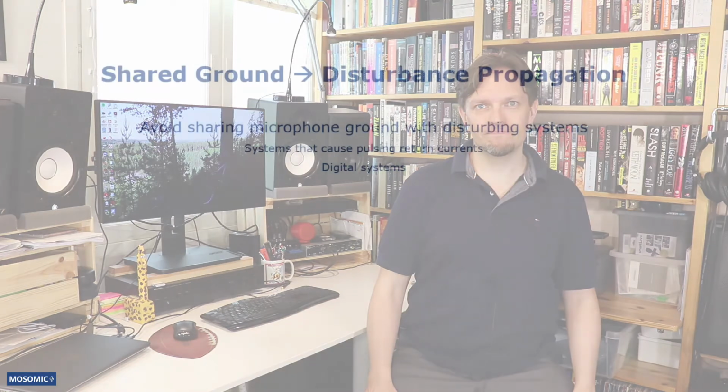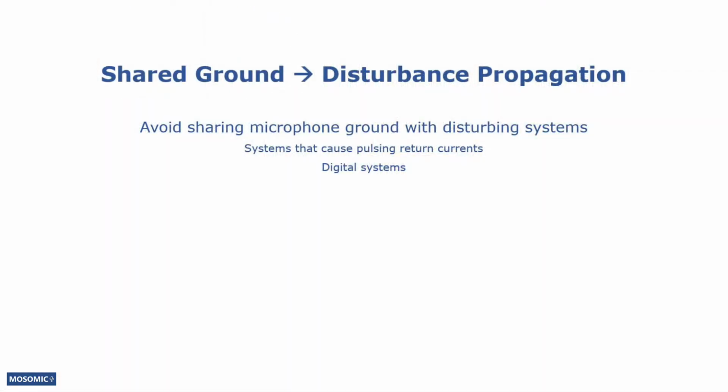Shared grounds are a common way for disturbances to propagate from one part of the system to another. Microphones should not share grounds with systems that are prone to cause disturbances, like pulsing return currents. Also, digital and analog systems in a device should be separated to avoid disturbances. Well-designed ground traces and ground planes help keep disturbance propagation to a minimum.